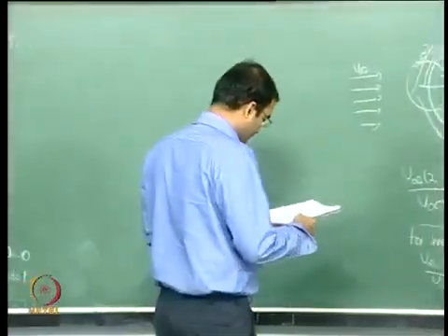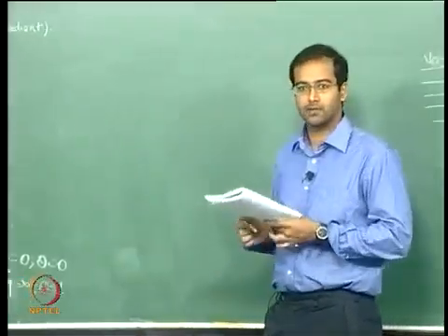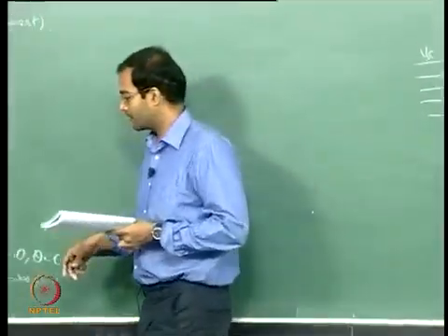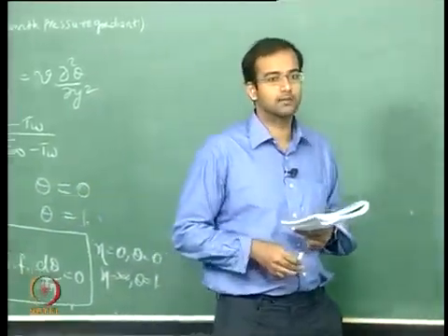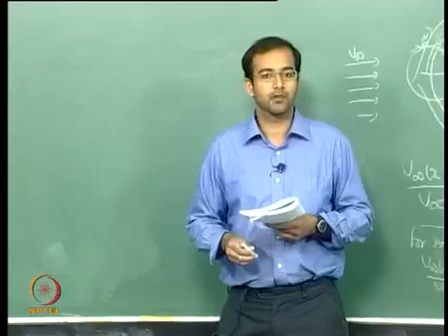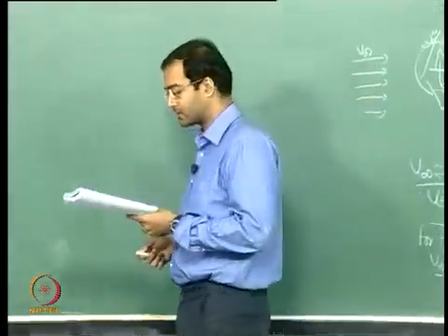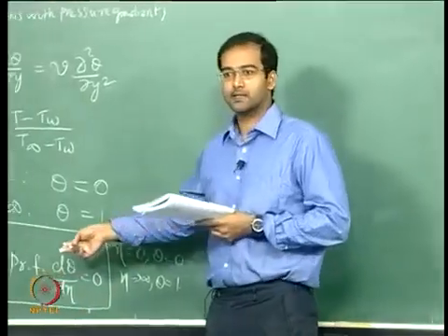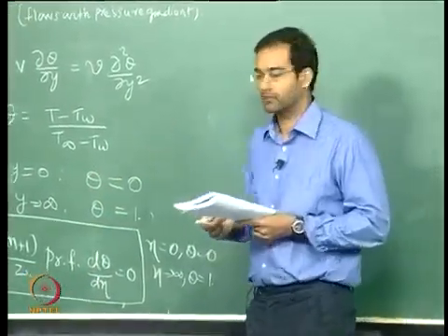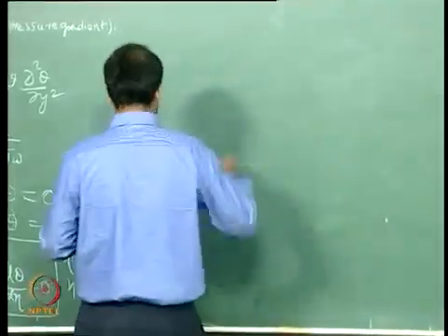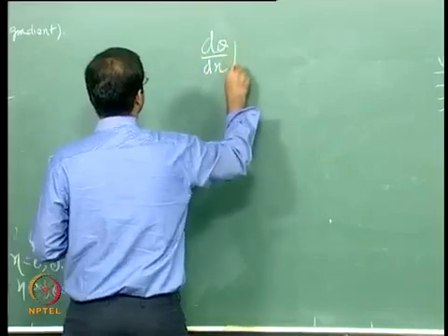Now what I am going to give is just the way we tabulated the curvature at the wall for the velocity profiles. Once you substitute and get the values, you can get the slope of the temperature at the wall for different values of m, for different configurations, because this is required to calculate the Nusselt number. The Nusselt number depends upon this temperature slope at the wall. So if you do the tabulation, d theta by d eta at eta equal to 0.